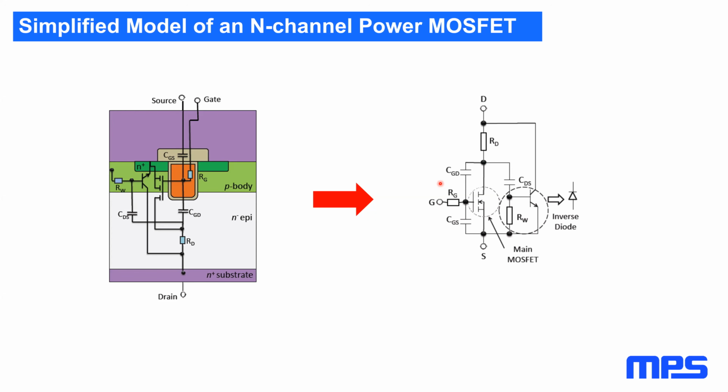So basically that means you have something limiting current. Whether the motor driver IC is doing a PWM ramp to limit the current, or something else is limiting the current, in any case, there's something limiting the current. So the only solution is to remove that current limit.